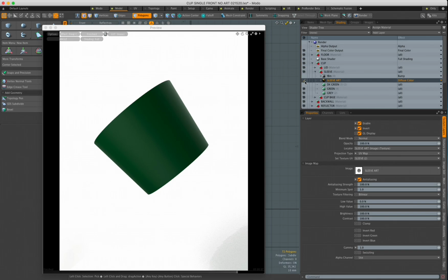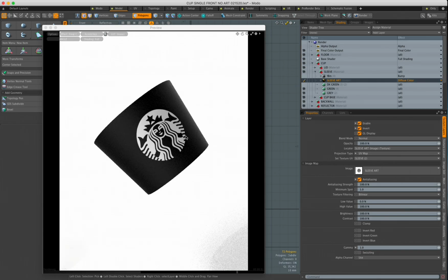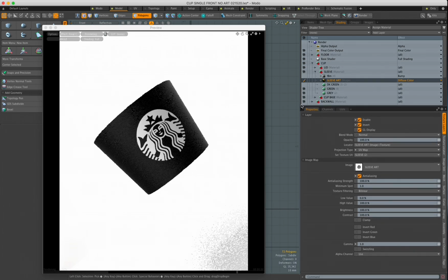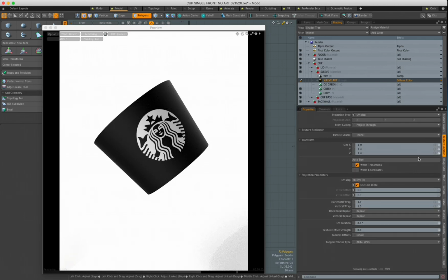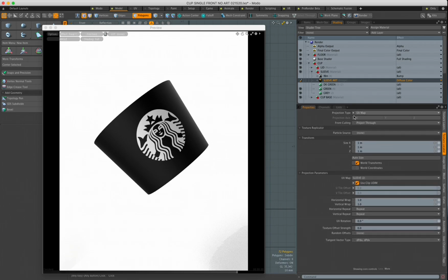So once it's brought in, it's just going to fall in position. I created a previous UV, and to know where they're at, just in case you ever have these problems, there's the UV locator. So you see the UV locator that we created for the sleeve. Previously, when I did it on 8, I had named it sleeve 2, so it fell in the position we wanted.